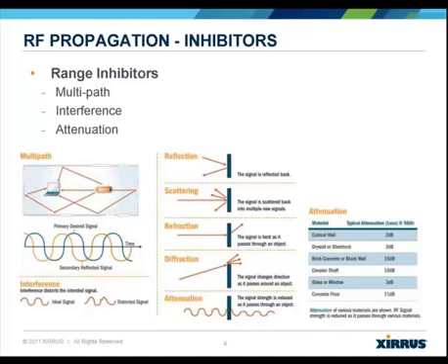These multiple copies serve to distort the received signal, rendering it weaker. This results in reduced throughput, or even in some cases, making the received signal completely useless. This is why you may have weaker signals in some areas of a room and strong signals only a short distance away.